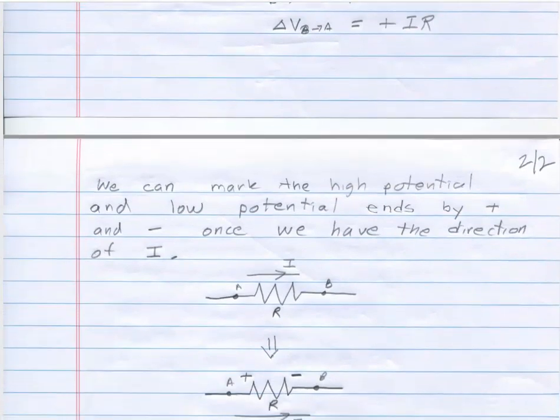And what I like to do is the following. If I have a resistor connected between points A and B, and I've got a current flow, or somebody tells me the current's flowing in that direction, or I've essentially assigned that as the direction of positive current flow across that resistor R, then based on that current flow direction, I assign a polarity to that resistor, and I usually indicate that with a little plus sign on the high side.